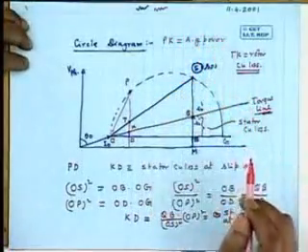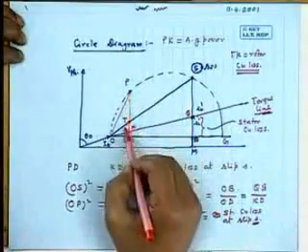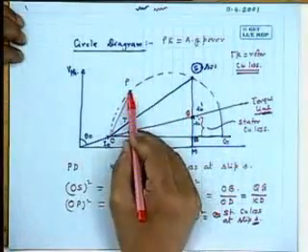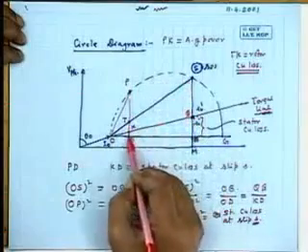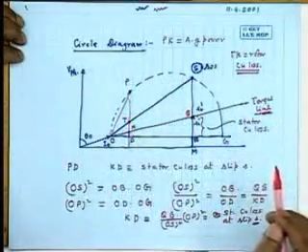So air gap power by synchronous speed gives you the torque. So any intercept, any line segment lying between the periphery of this circle and this line, vertical lines, will give you the torque produced at that slip.